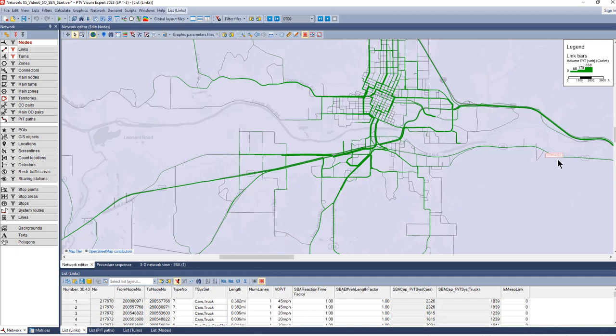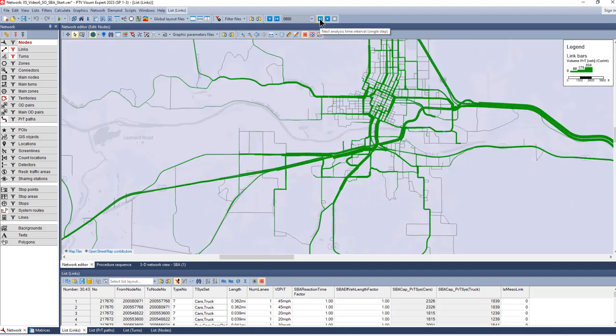So instead of having only the analyzed period, you have here also output for current intervals, it's called in Visum. Additionally, you find here a way how you can move through the time intervals. And by doing that, you can see the different volumes over time. So that is one way how you can visualize dynamic output from the simulation-based assignment.